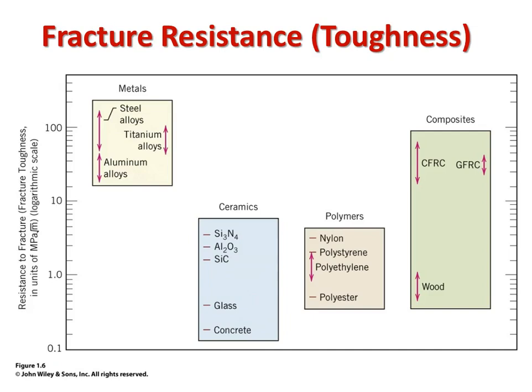But they do in fact have the lowest fracture toughness of any material, overlapping with polymers surprisingly. And there is a difference for the low fracture toughness of ceramics versus polymers, and we'll look at that quantitatively later on in the course. Ceramics are very high strength, but have very low ductility, and fracture toughness is effectively a combination of those two properties. In fact, it's the area under the curve defined by those two.